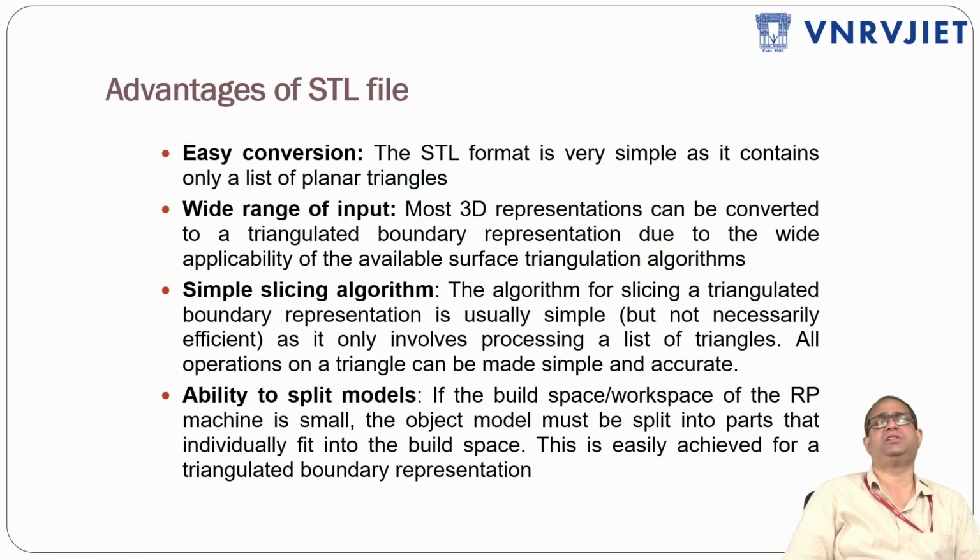Now, what are the advantages of the STL file? It is easy to convert. The STL file format is very simple and contains only planar triangles, and we can see a wide range of input. It also has a simple slicing algorithm, as it can very easily process the list of triangles. And there is the ability to split the models: we can split complex models into a number of